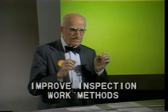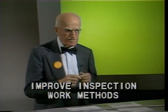Finally, we can improve inspection work methods and productivity. Conduct industrial engineering studies of inspection work to improve methods and establish standards of productivity. That's a long list. Now the high points of this session 13. Manufacturing planning should include early warning study of process capability. Manufacturing planning should include foolproofing. Foolproofing should include communications as well as hardware. Responsibility should be defined. Who is to do what?